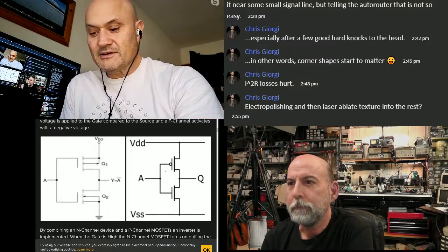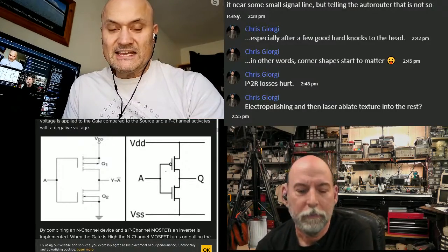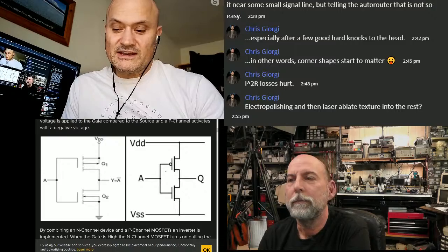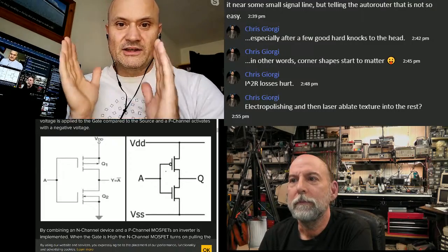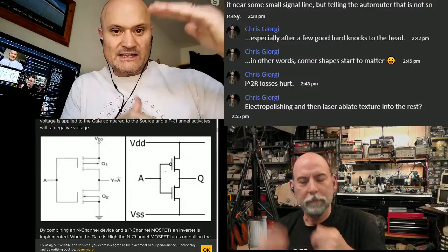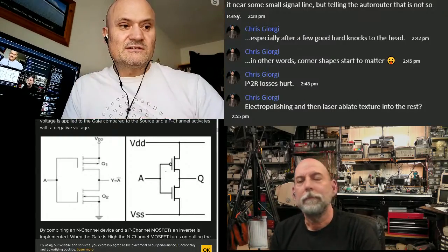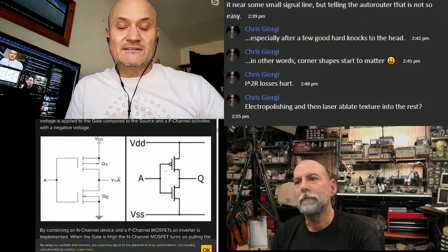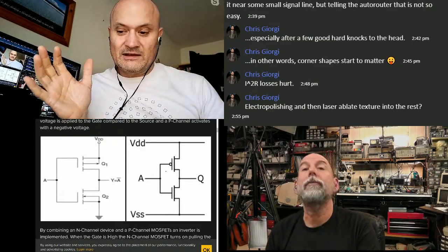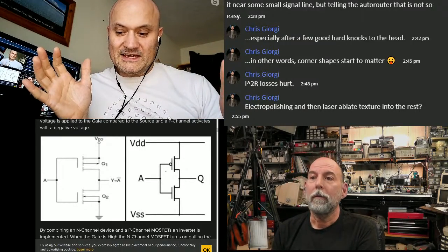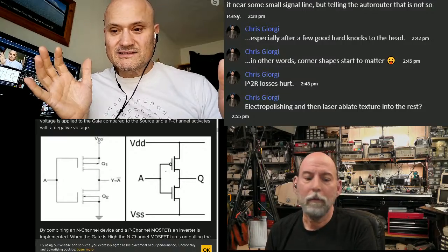So you answered your own question, but a fiducial is any board feature that is used for alignment and registration purposes, of the different layers of different films for the etching process, and of the actual board panels. They have fiducials. Yes. And it's also for pick and place machines.